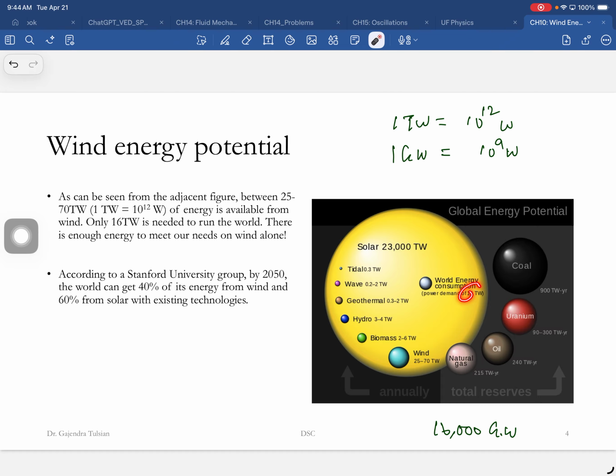Power in wind is proportional to the cube of the wind velocity. Let's make sure we understand this. The energy that you can extract is proportional to wind velocity cubed. So if the wind velocity doubles, 2 cubed is 8. The power available is 8 times as great.